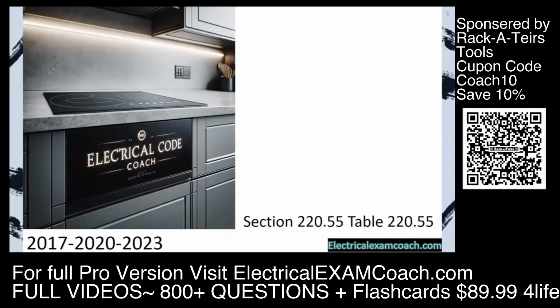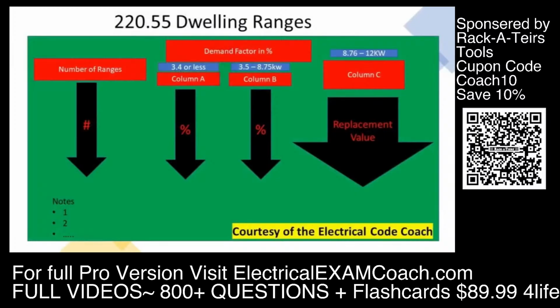Let's get to it. When we get to table 220.55, we're going to read the black bold heading at the top of the table to make sure that we're in the right table. Then, starting on the left-hand side, we're going to find our number of ranges: 1, 2, 3, 4, 5, and so on. Then we're going to notice that there are 3 different columns. They're really in 2 different groups. Column A and column B are grouped together under the demand factor in percentage column. The reason that's so important for us to watch out for is because column A and column B are multipliers. They're actual demand factors. But column C is a replacement value, and you'll understand more of what that means as we get farther through this video.